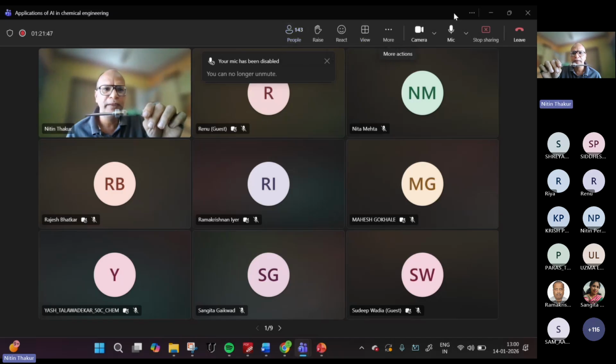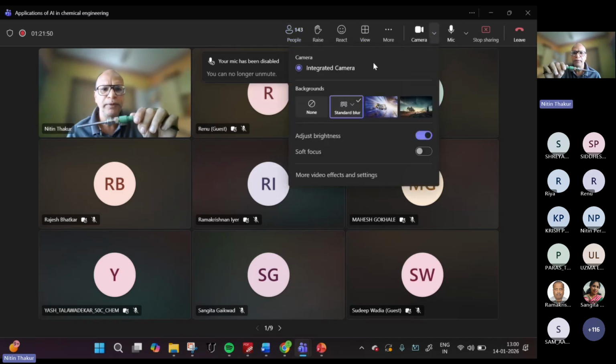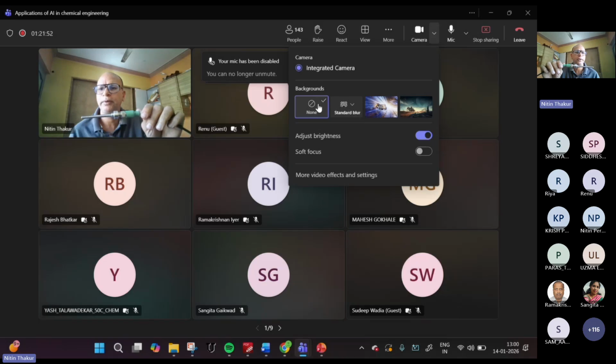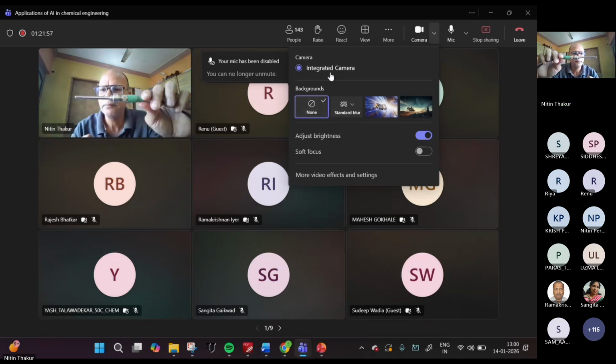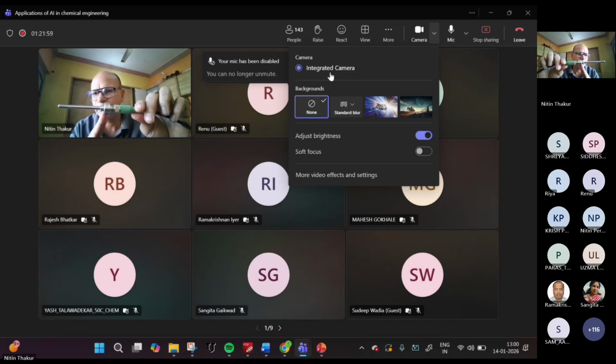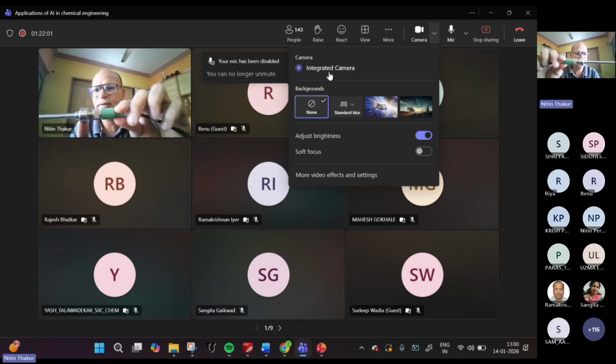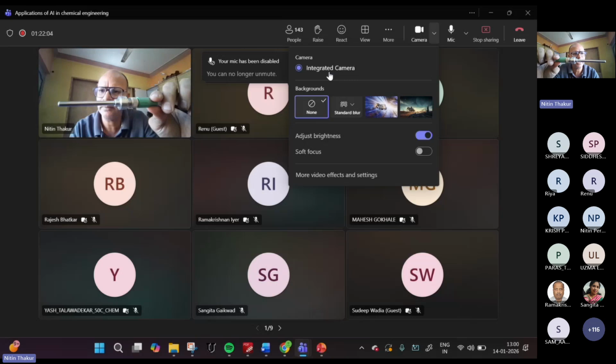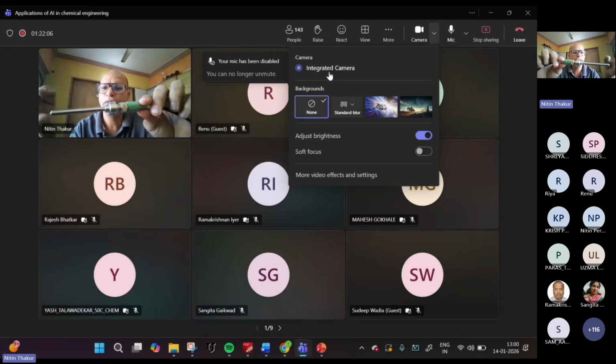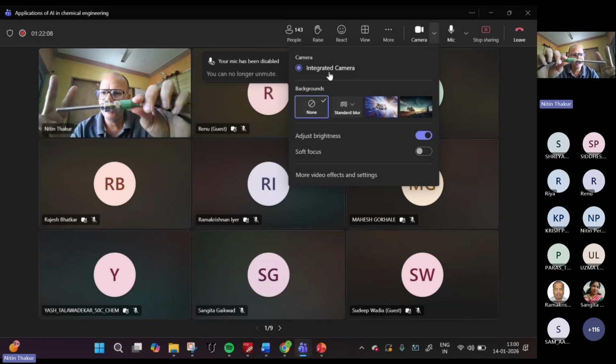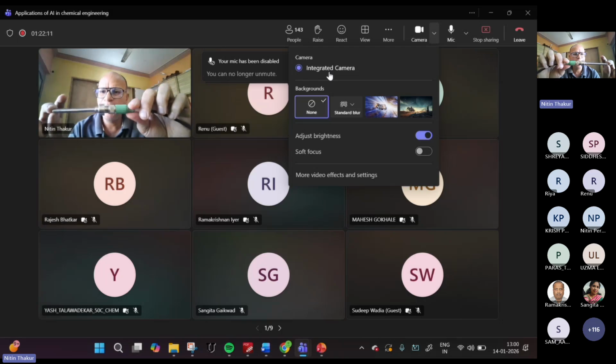So this is the PT100 temperature sensor, and this temperature sensor is by IFM. We use these two temperature sensors mainly to monitor the temperature of the cooling water going in and the temperature of cooling water going out.